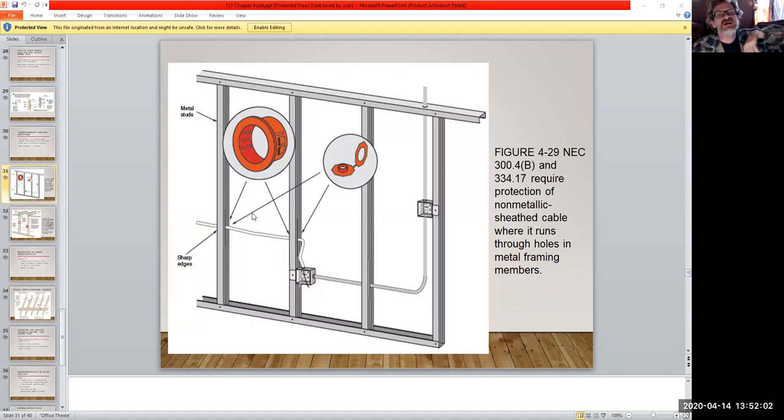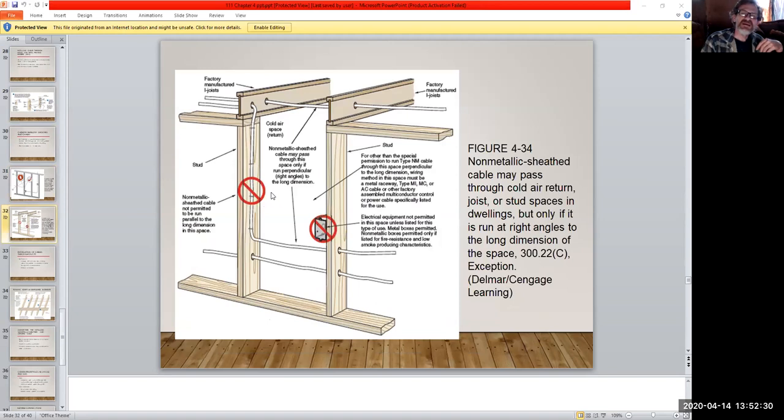So these little nylon grommets or bushings, you basically insert them in, and they even have a little fastener thing. If you look on the side there, it almost looks like little two-way tabs, and then it would have a ring, and the ring on the other side would basically secure it and hold it on. That way your cable's protected from slicing through the 2x4 over time. It does happen.